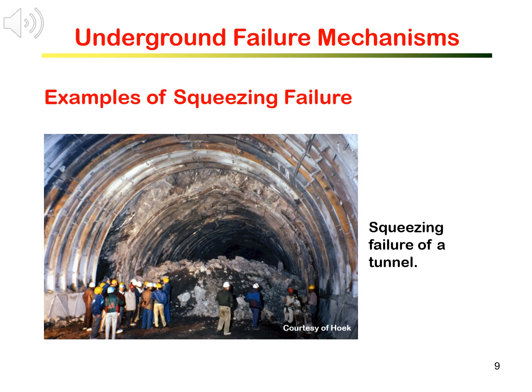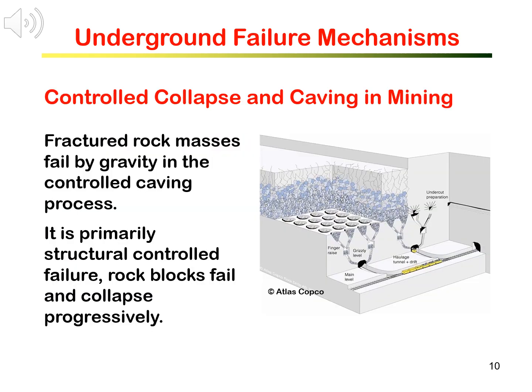Normally, the two key factors leading to squeezing are weak or poor rock mass and relatively high in-situ stress. Squeezing can also be due to the swelling nature of some rocks containing swelling minerals. In this case, the large deformation is caused by swelling of the material when exposed to wetting.